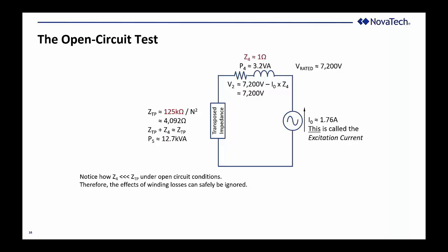And they go through the entire process. Now, nobody measures the ohms, and nobody says it's this many ohms resistive and this many ohms reactive. But just working in ballpark numbers, this gives you a sense of what's a high impedance, what's a low impedance, how much current is flowing through the circuit, and how much power is absorbed by that component. The power absorbed by that component represents either iron or copper losses. So this is how we determine the ratings and what we do with them once we have them.